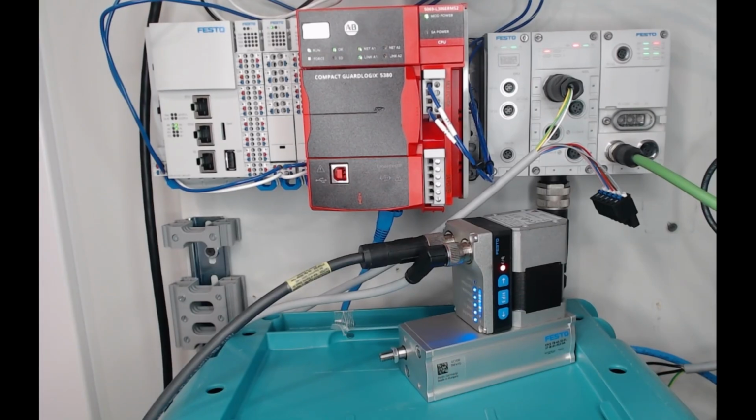They use a single-turn absolute encoder, which is a great lower cost alternative to an absolute encoder, but for linear motion, it requires a home move on the first power up. So for these motors, if you tell it to initially move out, it's going to perform a home move where it moves to the in position and then it will move out. And this kind of unwanted motion can be unexpected and possibly cause damage to your system.